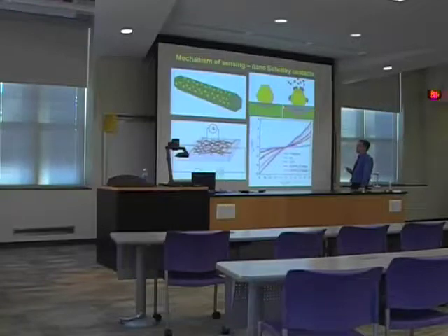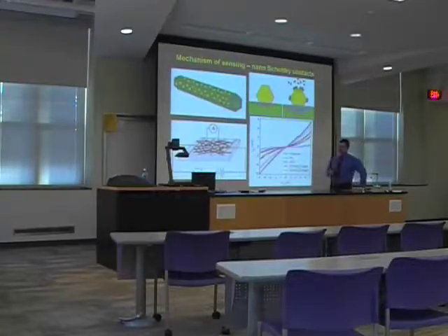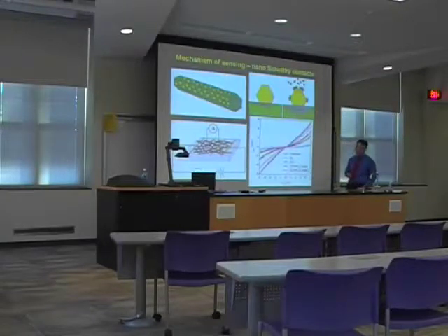So this is the mechanism of sensing, and it was explained in some of my papers. So when you grow a nanoparticle on the surface of the nanowire, it forms the depletion region right below it. It's a so-called nanoscale Schottky contact. The nature of the depletion region is to put the system in thermodynamic equilibrium, you need to equilibrate Fermi levels on the side of the nanoparticle and on the side of the nanowire.